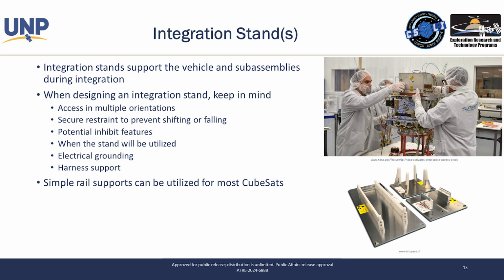It's really bad for CubeSat systems. Planning for how the entire... you can see these Delrin stands here on the bottom right, those are non-conductive. So if I place my satellite just on those systems, I now have an electrically isolated, very sensitive piece of equipment in a lab full of static electricity. So if I shuffle up and touch my CubeSat, I could actually cause ESD damage to it. So I need to plan a grounding route around that Delrin to the common facility ground.